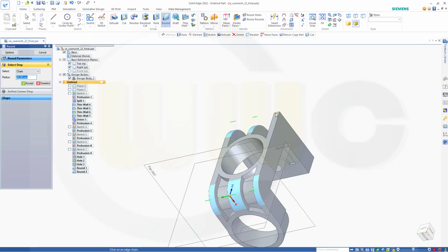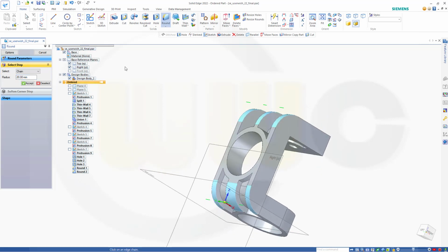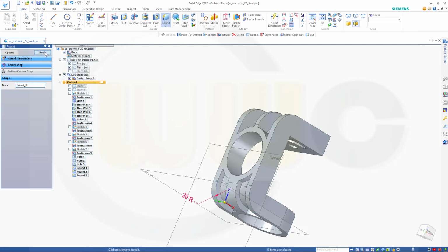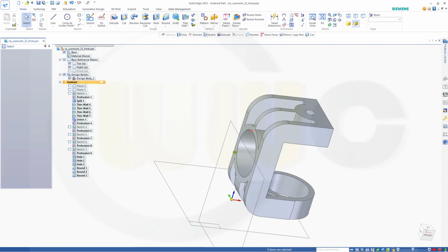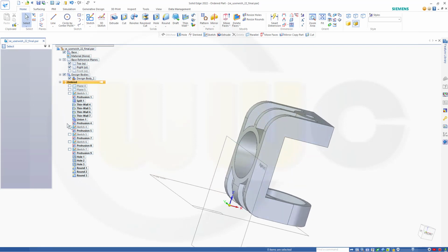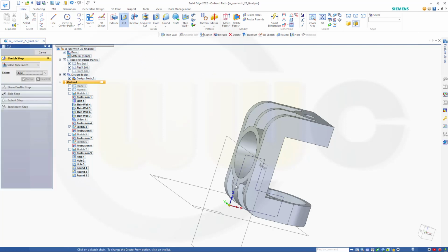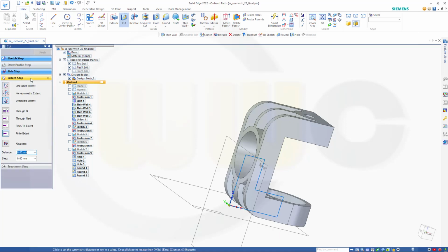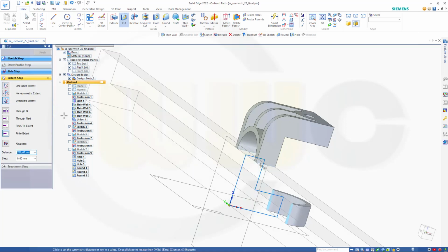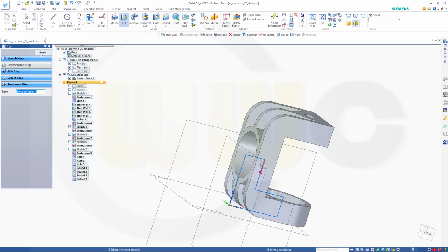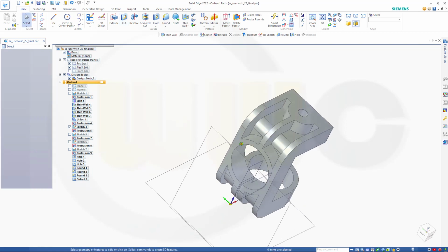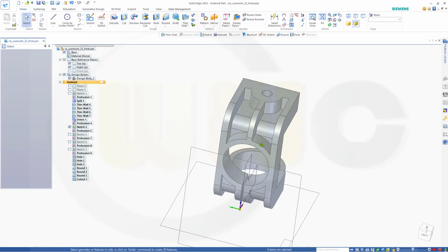And I just noticed I forgot to make the cut, but no problem, I can do the cut right now as well. So accept, preview, finish, cancel this out. I need to do a cut with the second sketch. That's this one. Yeah. Let's go for a cut. Make it symmetric. Yes, it is. And go for 2 millimeter. And finish. Cancel this out. Great.